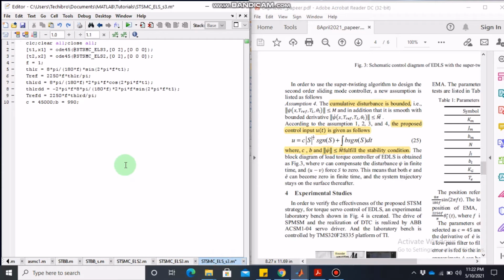And then we have the errors. So I call E1 as E11 because there will be 2 types of errors. One is the error due to sliding mode control, and the other will be the errors due to PID control. So I need to compare PID with the sliding mode, so I define the errors with different subscripts. So the sliding surface as before, E2 plus C times E1, except that E1 is now E11 and E2 is now E21.